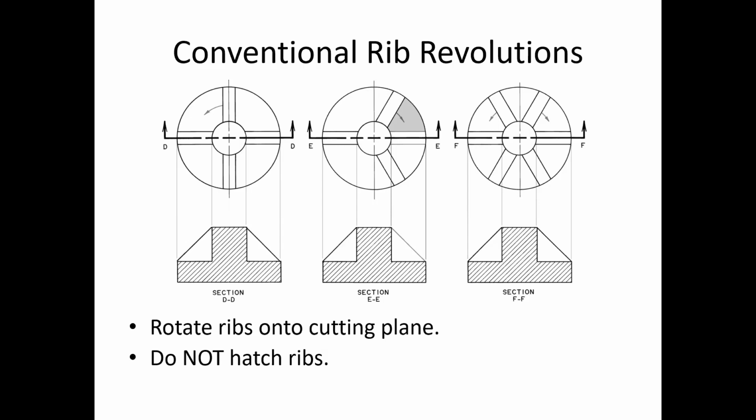There's a big dance that you can do to turn things off, and sketch things in and make it not do that, but it's a big problem. So, SolidWorks, if you model that as a rib feature, it knows not to hatch it. It can do this convention.